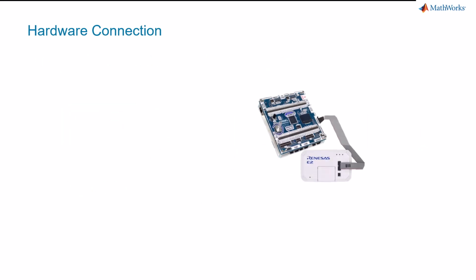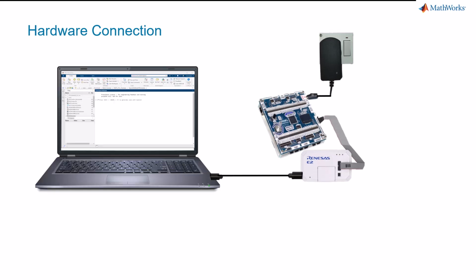Let's begin with the hardware connection. Connect the RH850 Starter Kit to the Renesas E2 emulator, power the board using 12-volt adapter, connect the E2 emulator to the host computer where the MATLAB is installed using a USB cable. Having the hardware connection done, let's move to the Simulink modeling.